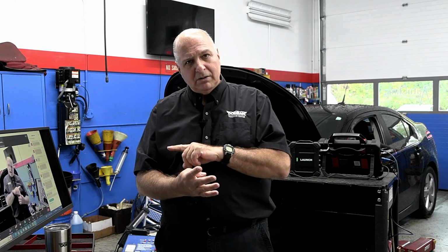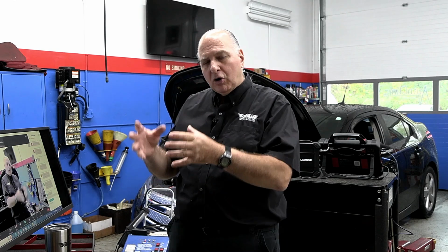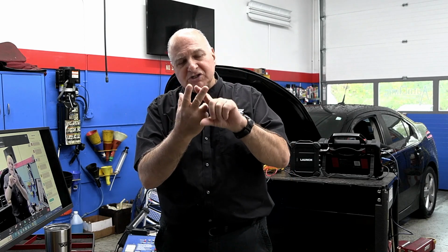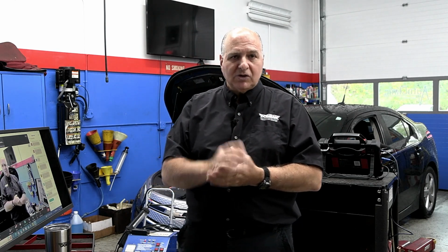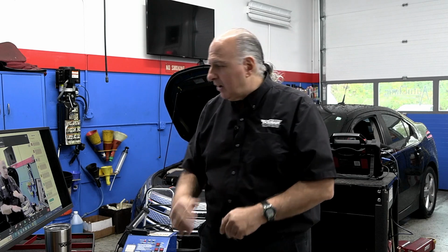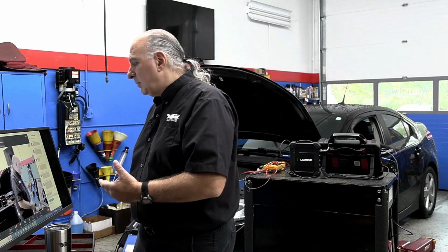And then the signal wire. If I go from a good ground, usually the battery ground, to that signal wire, I will read 2.5 to 3.5 volts. If I switch over to the signal ground, pin 5, I would read 0 to 1 volts. So that's a floating ground. We don't want to pull down on it. There are many companies that do that.